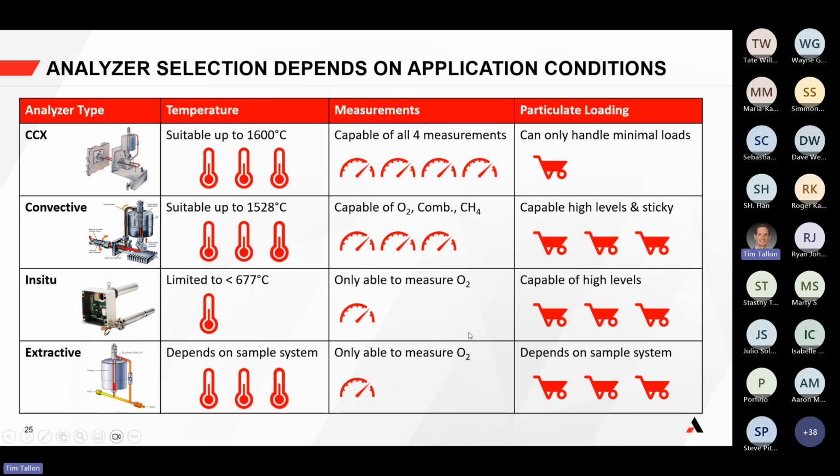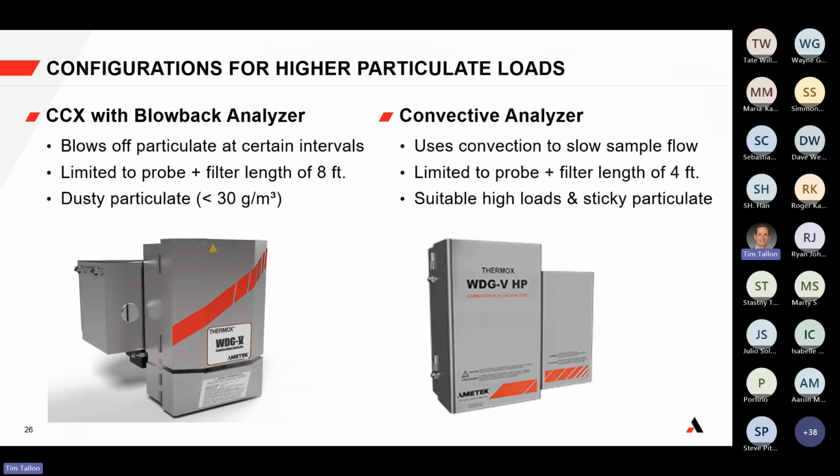So just as a quick picture, some things to think about if you're looking for lower loads versus more measurements, or higher temperatures and higher loads versus fewer measurements. So when it goes to even higher and higher measurements, I know I mentioned the convective analyzer, but I do want to highlight that as well as the close couple extractive type with blowback.